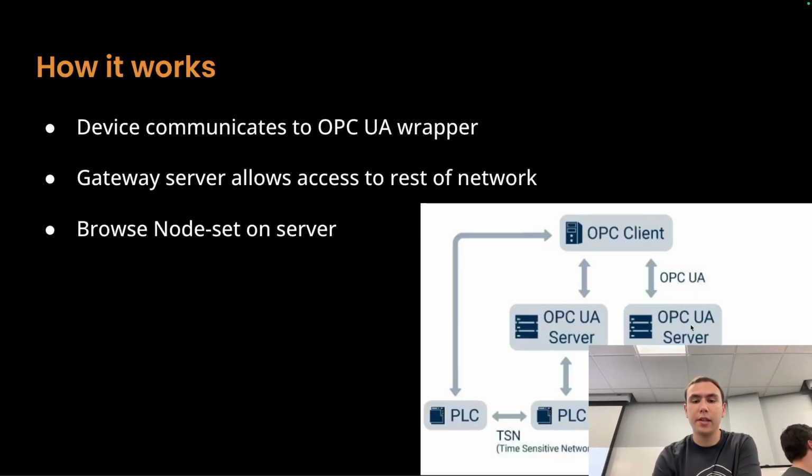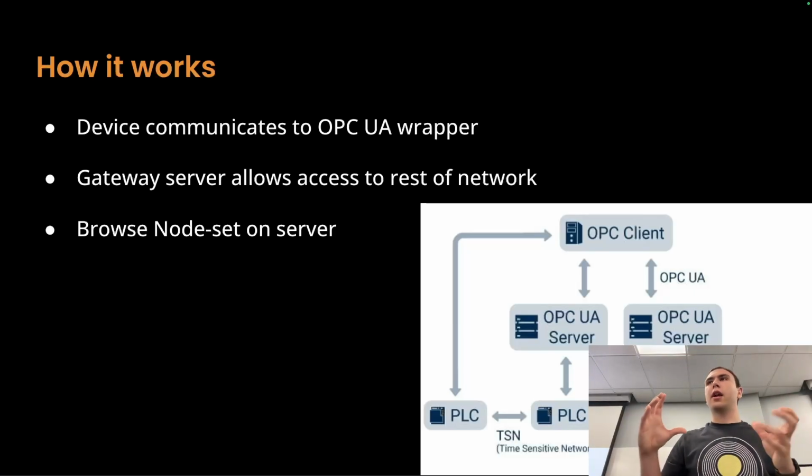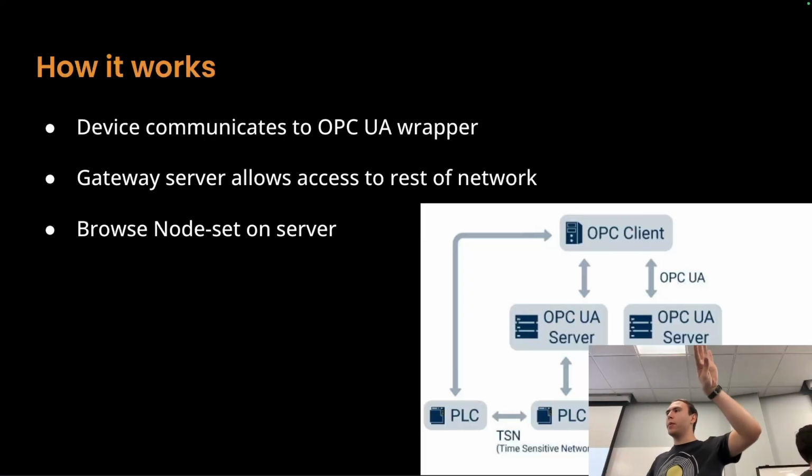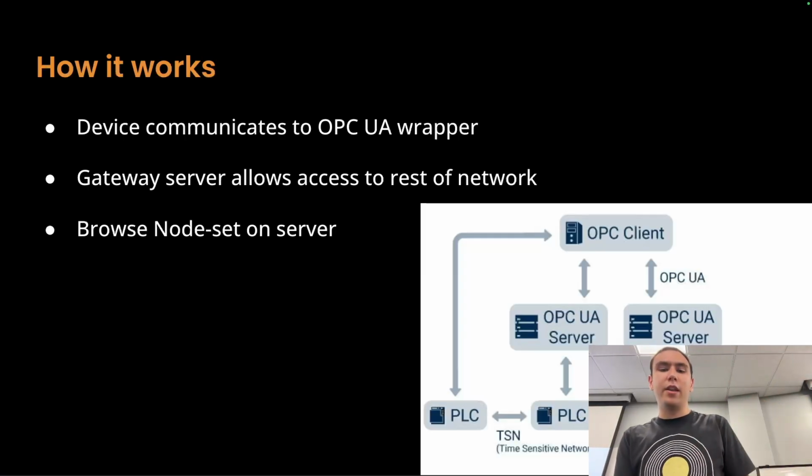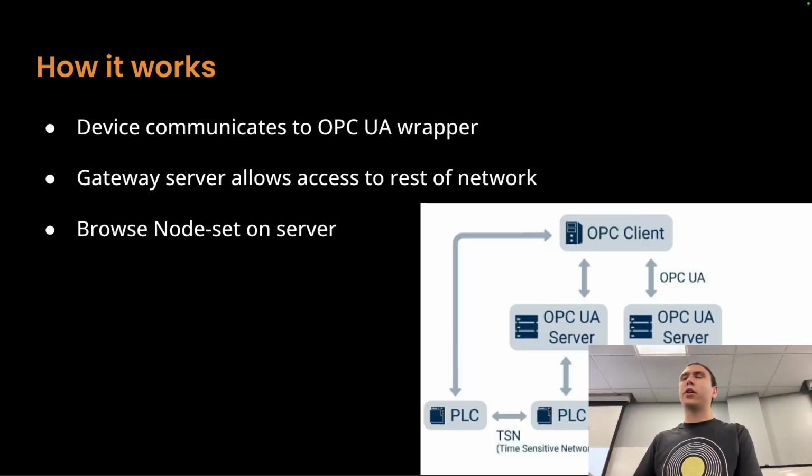And essentially what that does is it allows you to have something separate, taken away from the PLC, in order to provide the data from your PLCs or sensors or anything into a unified format that has security and some nicer features that you would expect when dealing with data, and not just this number 58 that's kind of around. Like with Modbus, you get the number 58, and you also get its register number 932, and you're like, well, that doesn't tell me anything. With OPC UA, the reason they did all this was to make it a better structure.